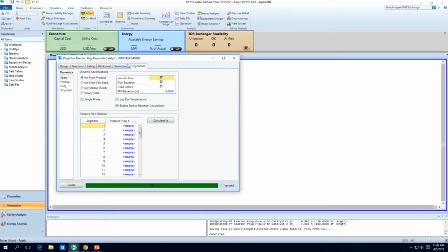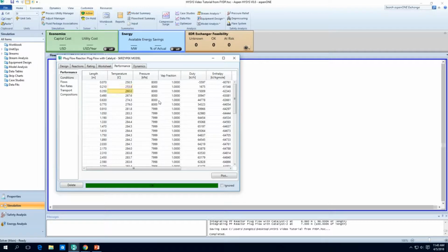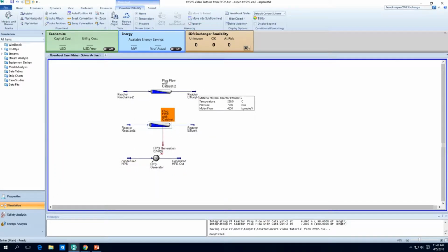With our reactor here, the top temperature is about 284, which is kind of acceptable, I suppose. Of course, here the temperature is like 286, which is slightly higher than what we wanted. But on the whole, the diabatic reactor seems better in comparison. So we'll want to start looking at our diabatic reactor, and we'll want to stick with it.